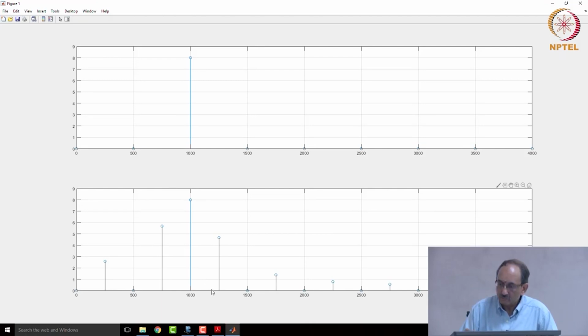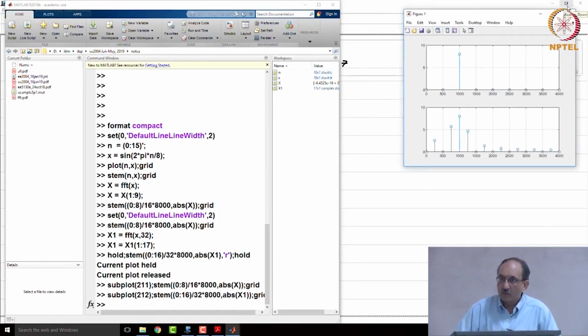Okay. To show that, let me plot the DTFT. I will plot the DTFT and show you the final plot, and then we will make a comment on that.